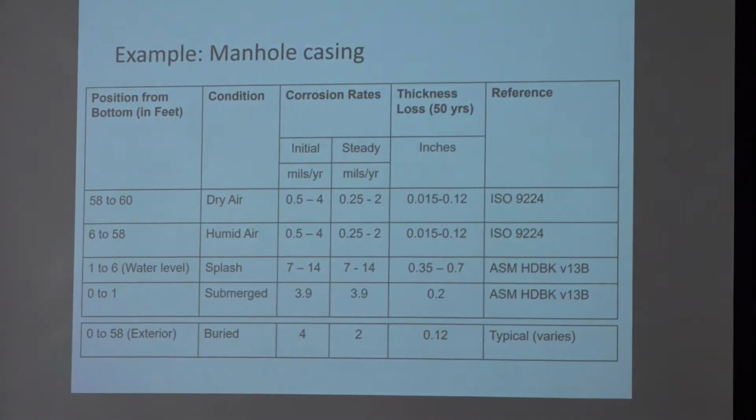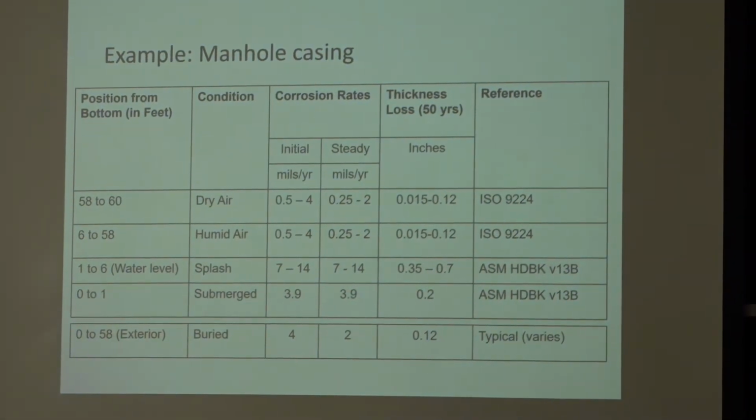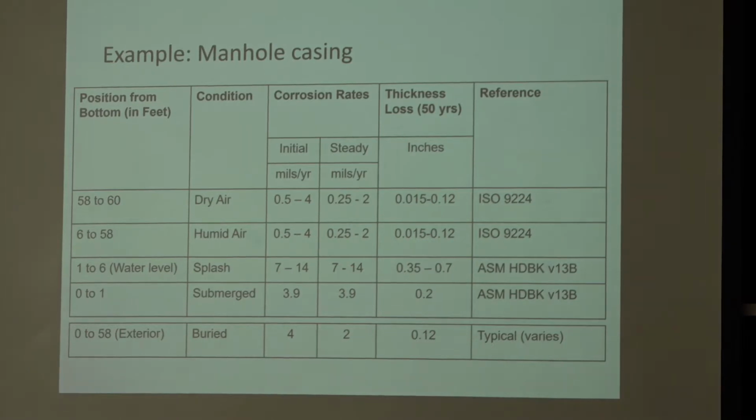But decide to bring in a little bit more of the engineering here. We're going to be using steel, and there was a discussion, I think it was last time, about using sacrificial thickness of steel on piles, for example. So if you bury big beams in the ground, you drive them all the way to the rock, and that's what's going to be the foundation for a building, for example. Sometimes you don't really provide corrosion protection if you put a paint. The paint will get destroyed when you drive through the big rocks and the dirt.